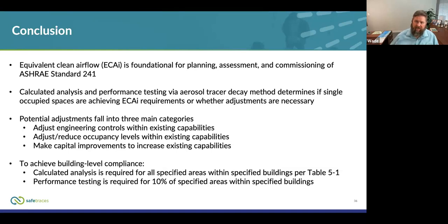In reality, we know, and there's a chart that everyone has seen for filters done by someone who's on this call named Bill, that shows that it'll actually remove particles of all various sizes, even at a MERV 8. In the calculator, we're not accounting for that at all. And it can play a big part. But when you're doing the in-room testing, the tracer testing, that filter gets to actually remove particles of the sizes that you would expect, and you'll see a benefit.